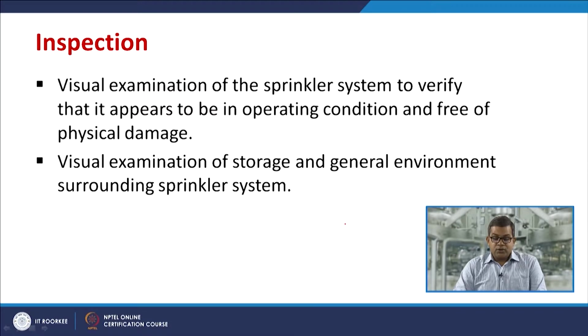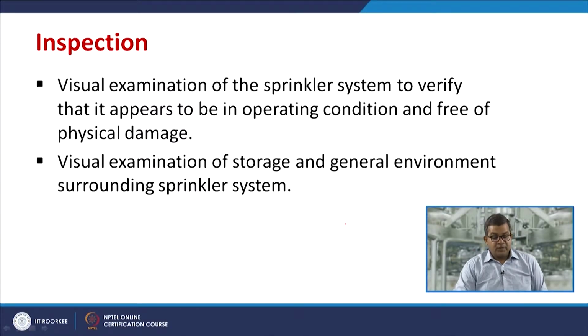Now let us have a look at the inspection. So, visual examination of the sprinkler system to verify that it appears to be in operating condition and free of physical damage. You can visually verify whether they are physically okay or slightly damaged. Also, visual examination of storage and the general environment surrounding the sprinkler system. So, you have to be careful while performing this physical examination.